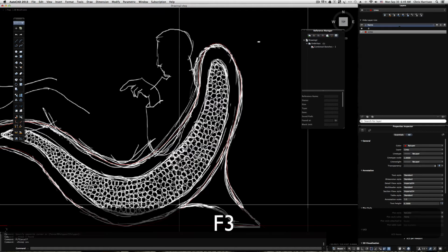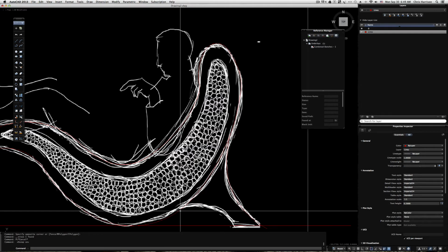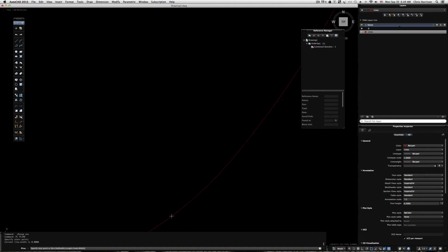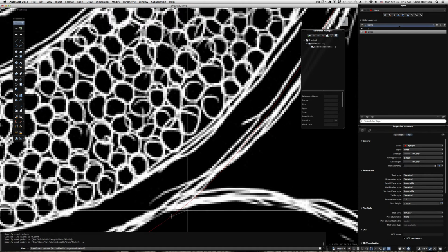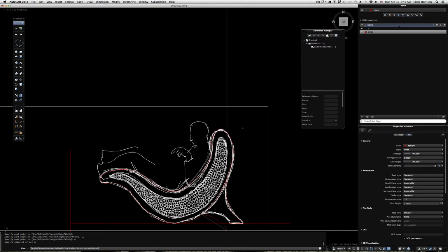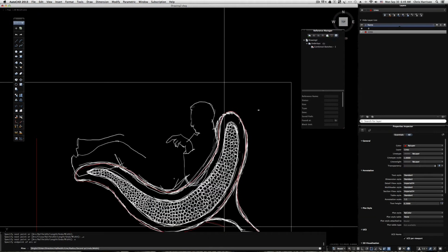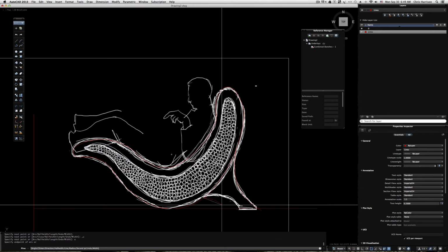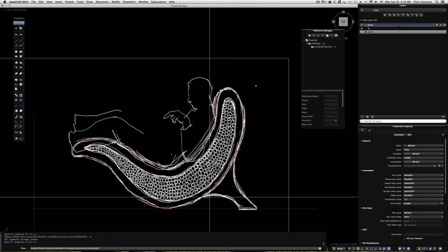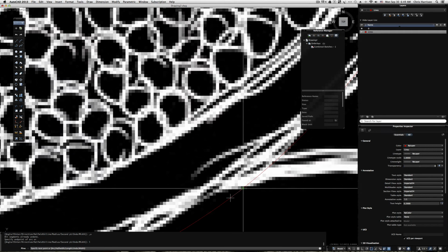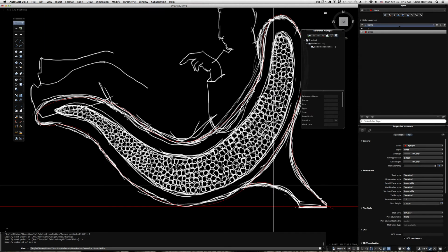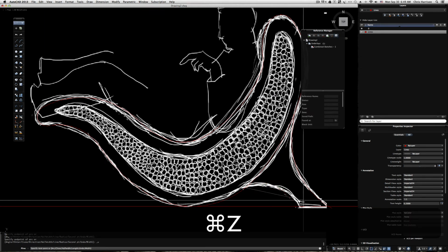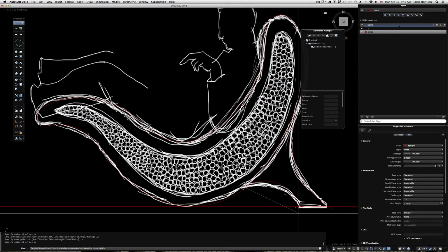So we turn back on my O snap. All right, and it's snapping. Zoom in. Oh, okay, so I'm not going to do a straight line segment and just hit A for arc. You see that it's not allowing me to follow that same shape. It's immediately creating an arc from that point. So typically when you draw these things, you want to use it with a straight line segment first. So I'm going to come up here and hit A. And actually I should just sweep that thing straight down. Hit A again. And that's good.